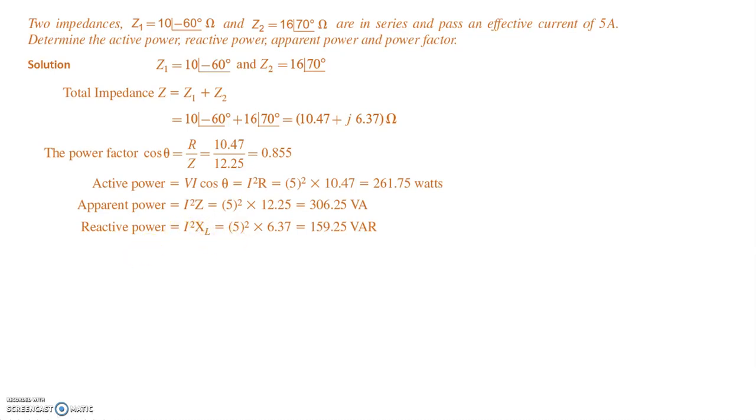When voltage is known to us, we can directly compute S by means of V into I conjugate, and the real part of S will give you the real power, and the reactive part of S will give you the reactive power.